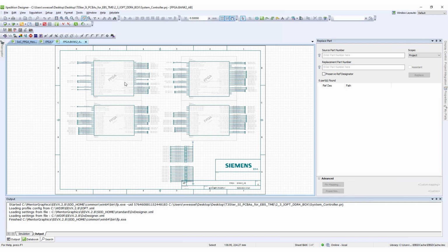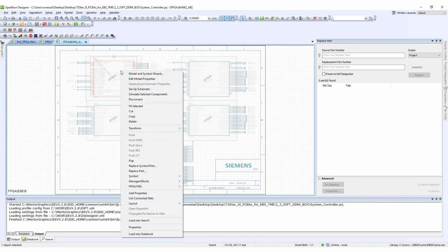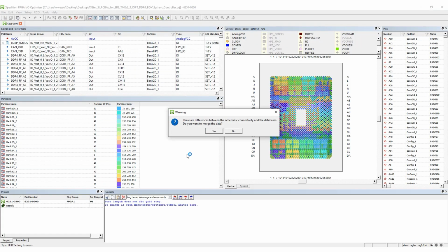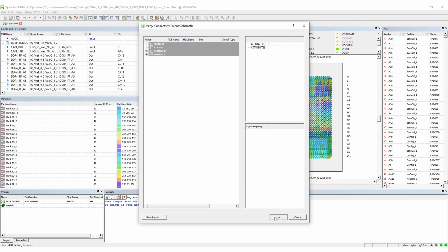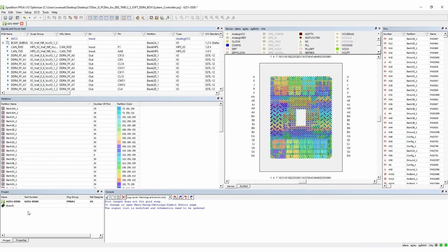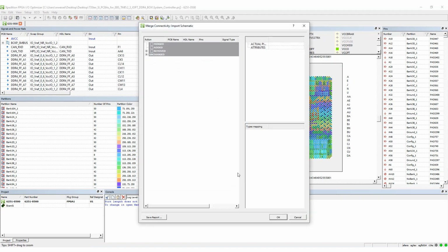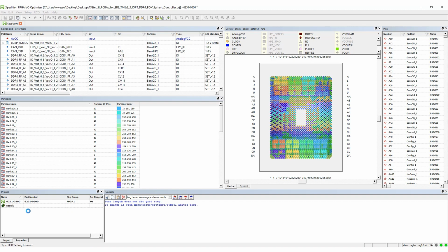I/O optimization is accessible at any stage of the project using the Xpedition schematic environment. The I/O optimizer is directly associated to the FPGA symbols. This saves a lot of time searching for commands in menus and toolbars. The main advantages of the integrated I/O optimization are that it knows all the FPGA vendor rules for pin assignment and swapping, and that it is PCB aware.